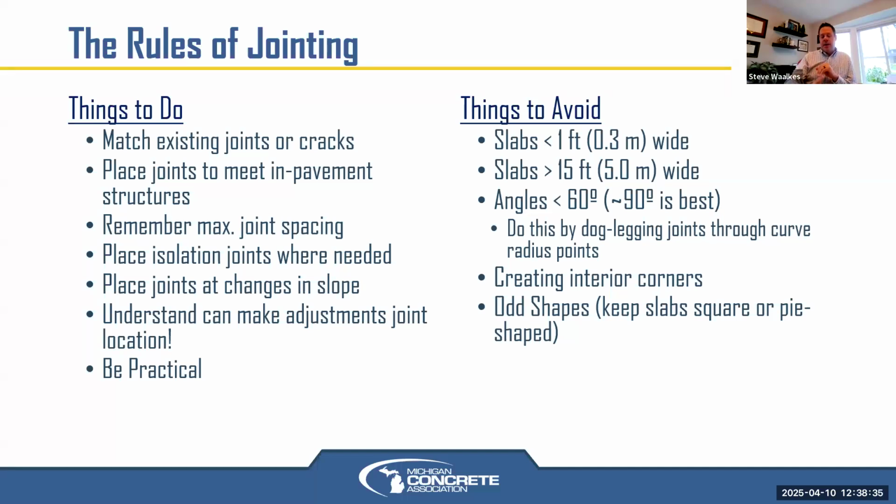I would probably try to plan for a joint, technically a transverse joint, going across that drive approach that lines up right over top of the center line of that culvert. Because I have seen it where we have some heaving or settlement or differential support or whatever it is, it's probably a good idea to do that over top of that culvert in those situations.